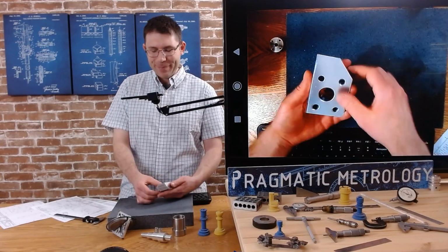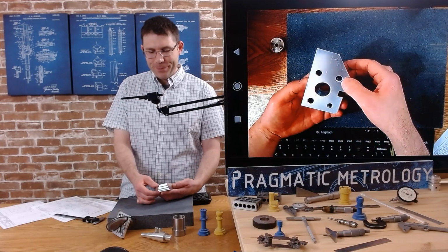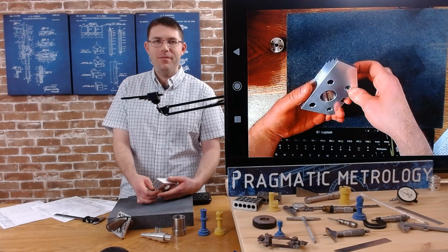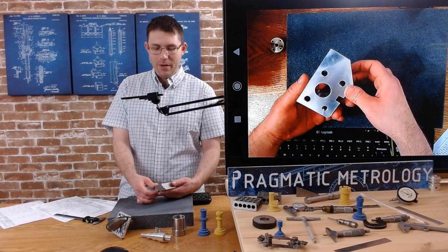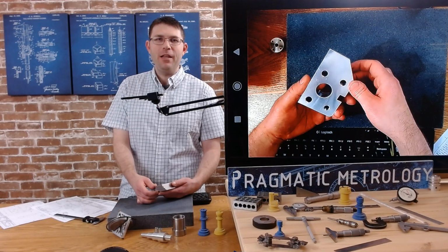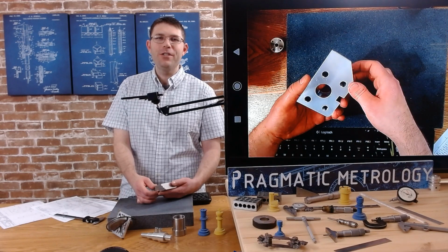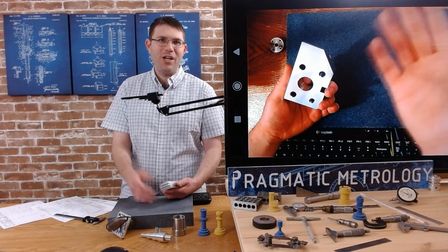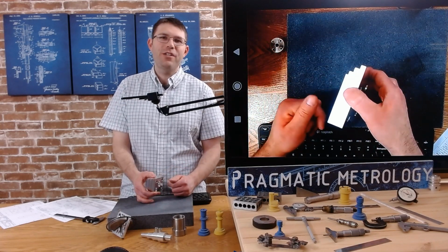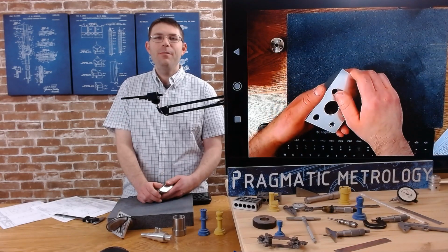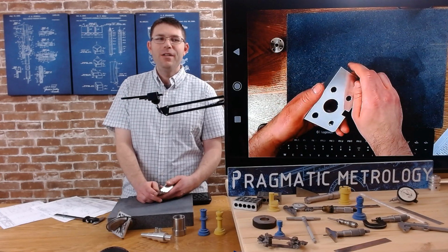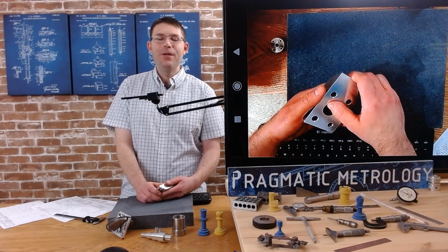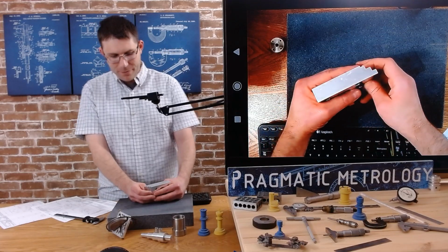But I've inspected probably in the thousands of parts where they put datum A in last on like a 4 or 5 operation, and as an inspector, it's frustrating because you're doing shop math the entire time. You're doing all these substitution checks the entire time. At the very end, they put the final datum on, and you wish production would do it in the other order. You wish they would do datum A first.